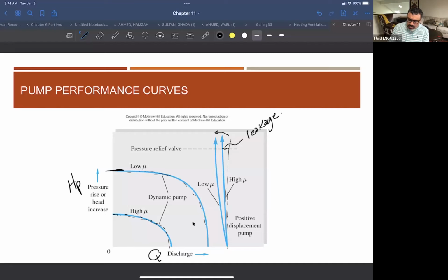It goes to a maximum here, right? Even when you close the valve, that means you have Q equal to 0, you have a maximum pressure inside the pump. And with this maximum pressure, you can actually design your casing based on it, right? So you don't have any problem with the damage of the pump or so on. That's why you see many applications where they have a valve at the delivery side of a centrifugal pump, and you can even close it completely for the whole shutdown of the system without any issue.